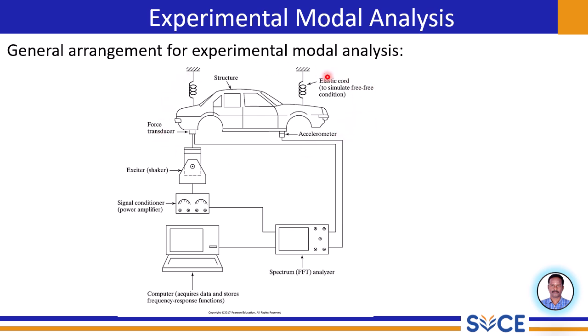This allows us to identify its inherent modal properties without significant influence from external supports. Below this, you can see an exciter or shaker. This is attached to the structure via a force transducer. The shaker generates the controlled dynamic force that we apply to the structure at a specific point. Here, the force transducer is crucial because it measures the actual force being input into the structure. This measured force is a very important signal and will be input to the signal processing equipment.